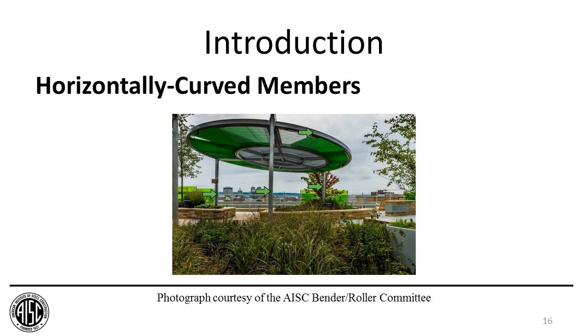So that tells you one thing, because the HSS members, once we get to session number 3, we'll talk about the torsional strength and stiffness required of these members. And if you look even closer, you'll see that those are end plate connections to the supporting post there. So let's kind of keep that in the back of our mind for session 3 once we talk about the horizontally curved members and connections.